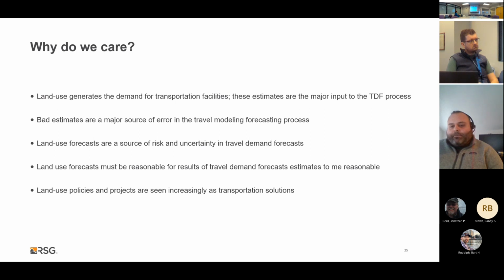So it's common for us to say, hey, there's capacity in the zone. We can see that maybe only 50% of the zone is at capacity, and then we allocate into that zone, but then we later find out that half of that zone is protected wetland. And no, you can't put any more population in that zone without changing the underlying land use planning activities. So we want to overlay what this area is zoned for and the reasonable way that this area can grow, and that is going to determine what kind of land use forecast you get.